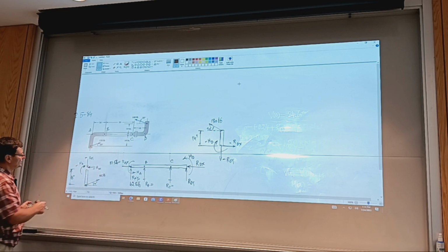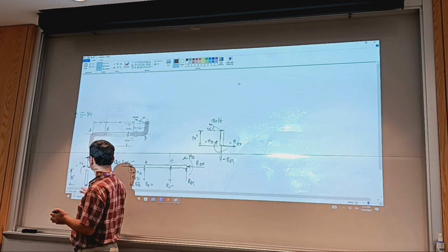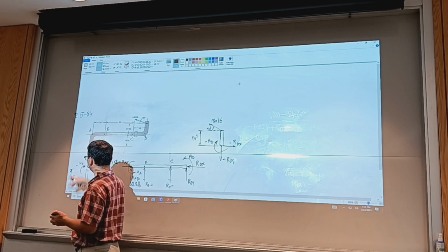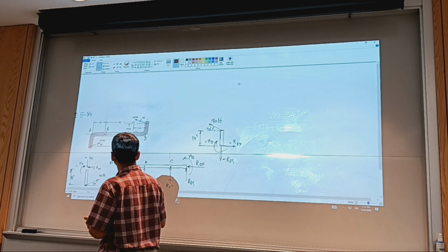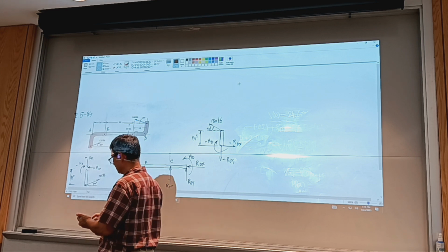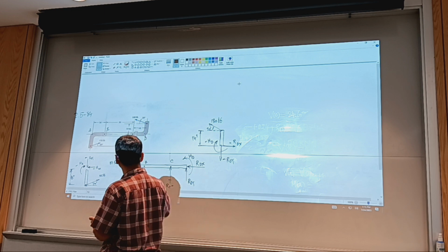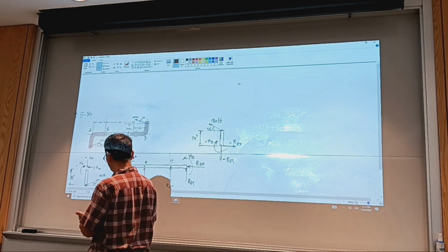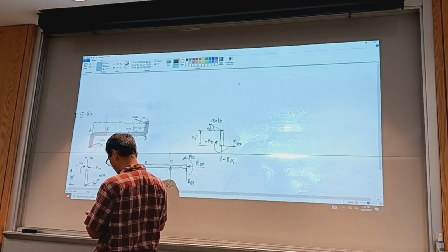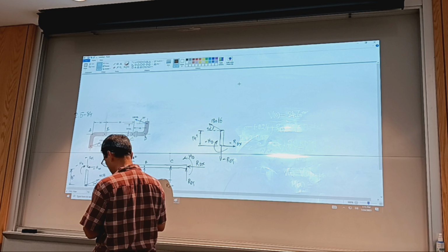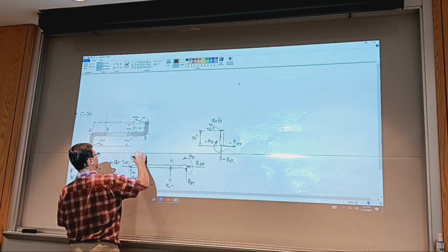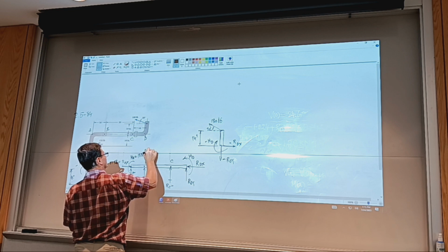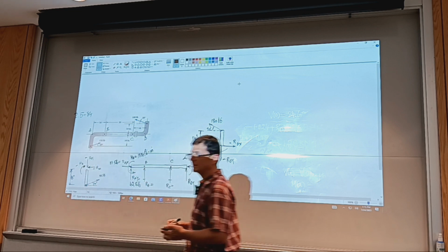And as for the moment, the force that causes it, of the x and y components, the x component does a moment, and the arm of that force is 16. So it'll be this one here times 16 gives me the MA. All right, so 117.5 times 16 inches is 1880 pound-inch of moment. Was it clear?